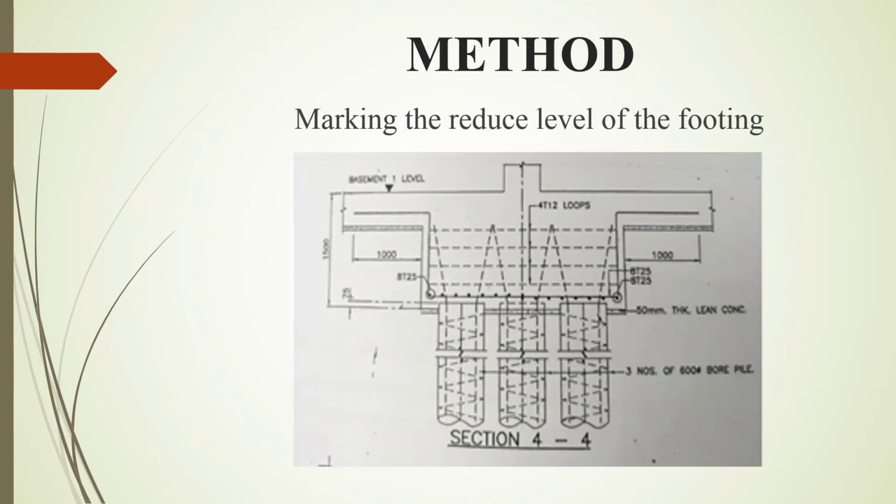Marking the reduced level of the footing. Before concreting the footing, the reduced level for the top of the footing must be marked by the surveyor. The finished reduced level of the top of the footing is shown in the construction drawing.